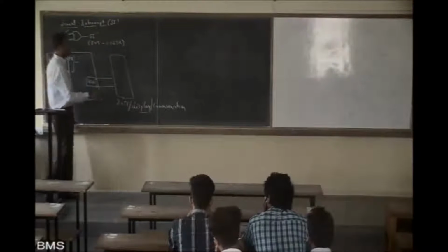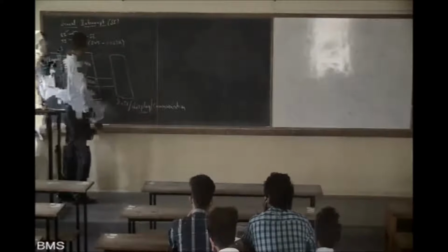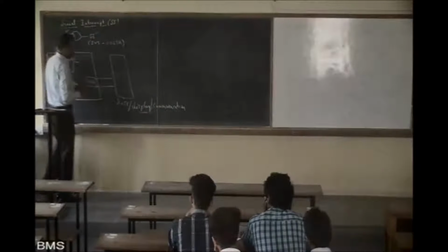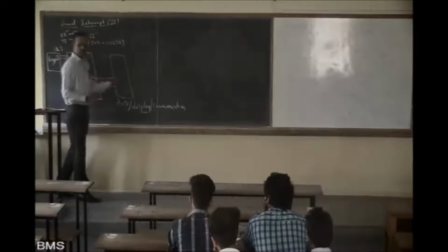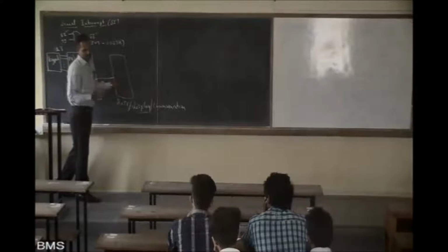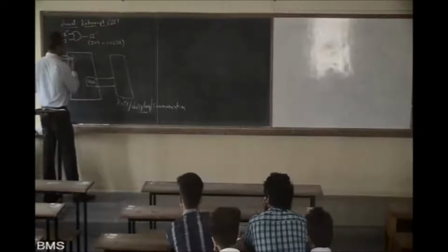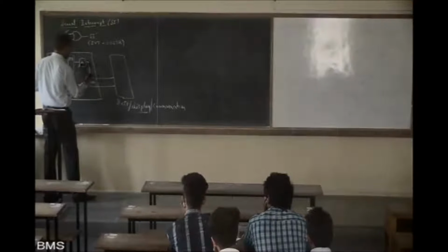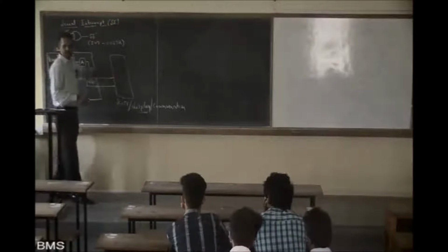So, not display, 8051 only. Another 8051. If I type 23, that 23 has to be sent to SBUF. From here it has to be sent to another 8051. This is a continuous process. What do I have to do? Read from port 0, put it to A, to SBUF, continuously.